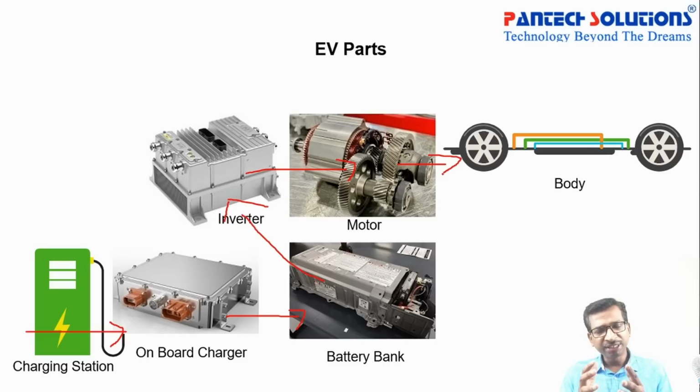So generally for EV systems, so far people are using lithium-ion batteries. In the market you can get lithium-ion batteries in any range like 12 volt, 24 volt, 60 volt, 72 volt, 80 volt, 100 volt, 96 volt. Any range you can get, because it's available in a single cell. So you just buy the model and then add it in either series or parallel based on your requirement.